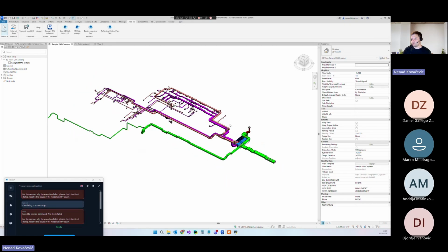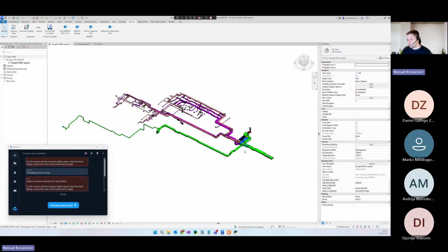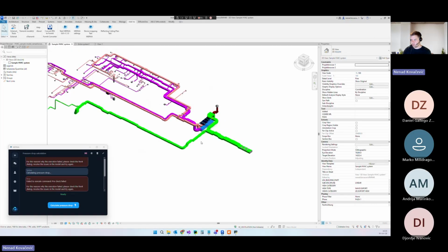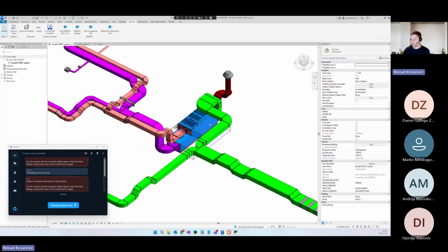So now we did fix everything, and now we can start with the calculation, but also for the fresh air over here, we basically have the shared system of the fresh air for different air handling units. And over here, I will show you how you can overcome this problem and just take the part of the network which is suitable for that air handling unit.